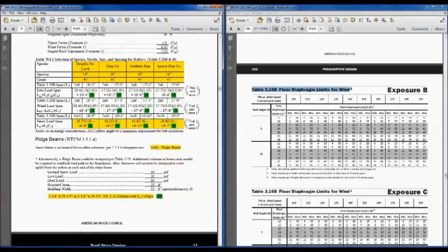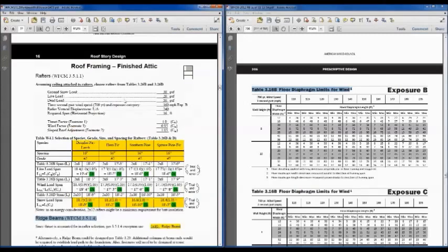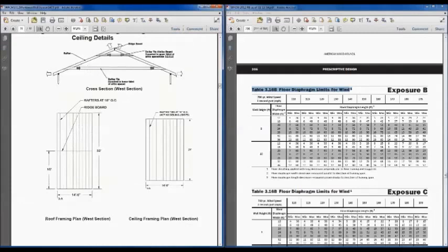What the ridge beam allows you to do is eliminate that ceiling joist or rafter tie. So it allows you to eliminate this bottom member right here. But that's all that a ridge beam would allow you to do. You still have to tie the rafters together up here at the top, even if you've got a ridge beam. So you'd have to come across the top with ridge straps, or you could come underneath the ridge beam if you want to hide it with this collar tie, and the collar tie then ties those rafters together.